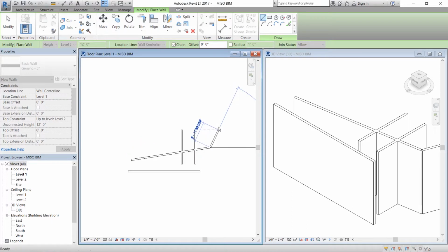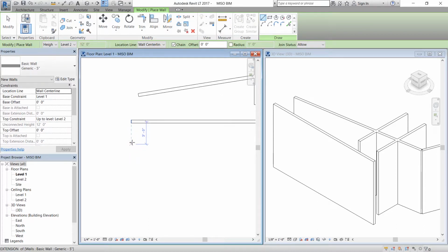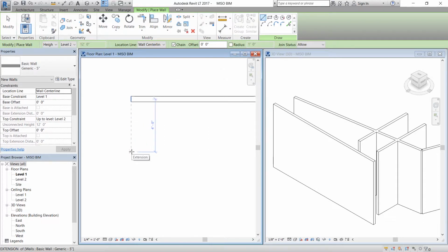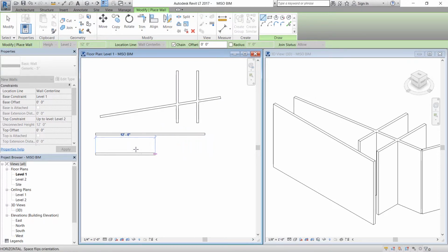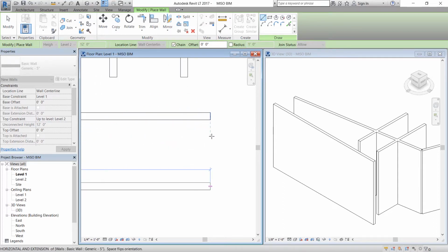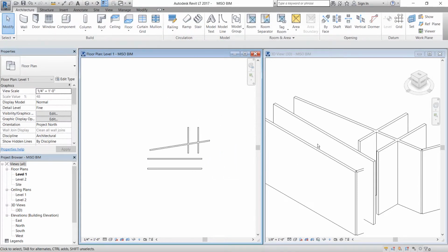Create another wall and let's take advantage of our snap settings. You can snap to the edge of a previous wall by hovering over it before you place your start point. You will see a blue dashed line as you move your mouse down and a temporary dimension from the center line of that wall. Move your cursor diagonally and then press and hold onto the shift key. Now your wall will only move in an orthogonal direction. You can zoom in or out while holding the shift key, but if you have to change your view, just let go of the shift key, fix your view's zoom extents, then press and hold shift, and finally set the endpoint to snap to another wall's edge. These are just the basic 2D placement of walls.